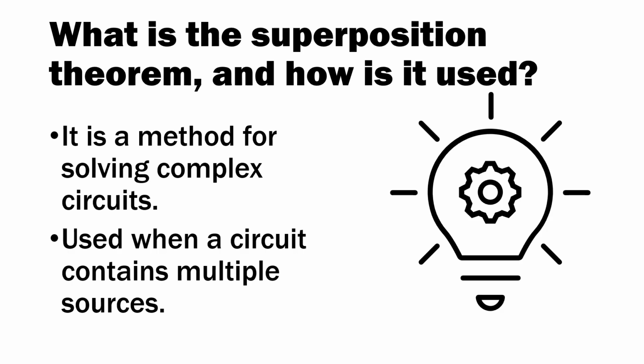The superposition theorem is used to solve complex linear or bilateral circuits, which are composed of multiple current and power sources, and components arranged in parallel and series. In the simplest definition, the superposition theorem removes power sources so that each power source can be analyzed individually, then each source is added together algebraically to finally demonstrate the effect of all power sources in the circuit.